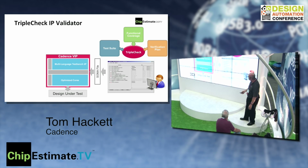And not only that, but triple check also pares down the test suite to select only the tests that are applicable for that kind of design, for your root complex design. So our test suite has thousands of tests in it, and maybe a bunch of those don't really apply to your design, right? Because it's got to cover all different configurations. Well, this will, like I said, pare those down to just the ones that make sense.